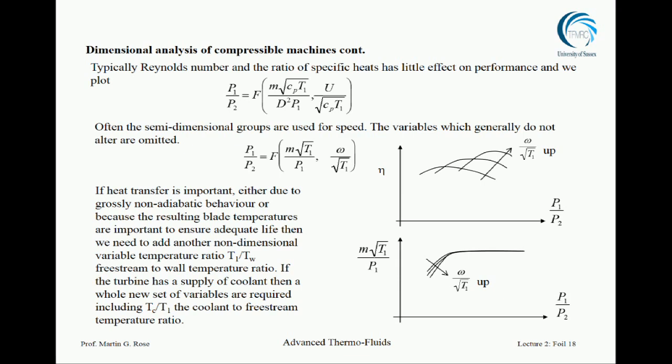This section mentions what I've already said to you about temperature. If it's a machine with heat transfer, you have to take into account the temperature ratio between the fluid and the outside world, which is represented by the wall temperature in this case. And if it's a cooled turbine, so you're squirting cold air in as well as hot air, then you need to take into account the temperature of the coolant, which is non-dimensionalized by the free stream temperature. I won't go into detail on that, but it comes in.